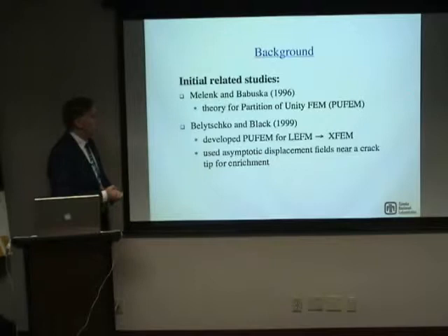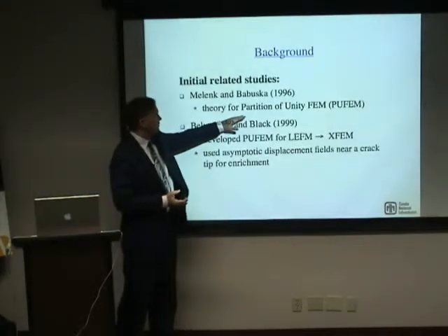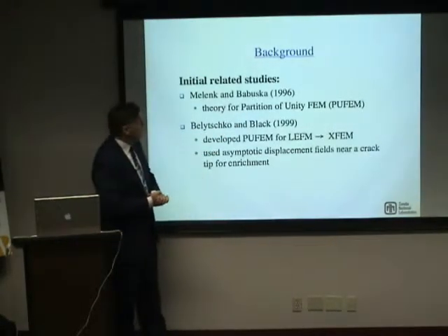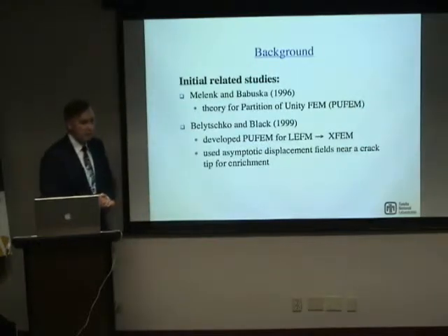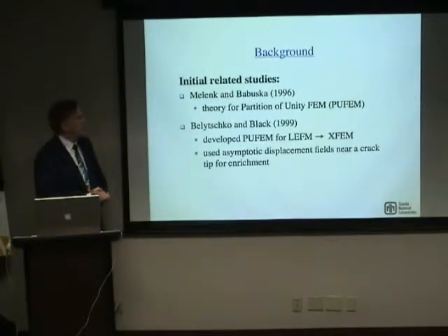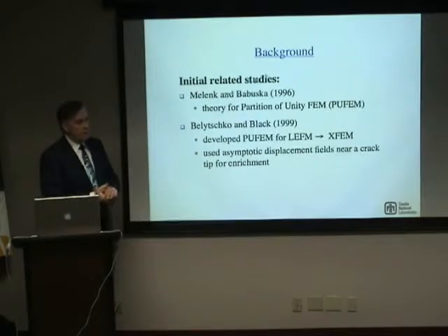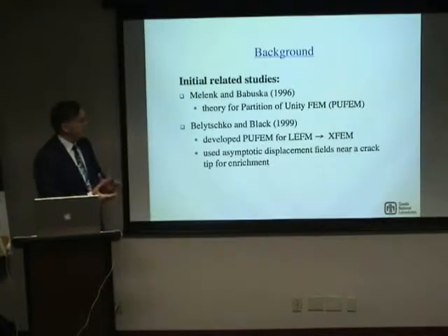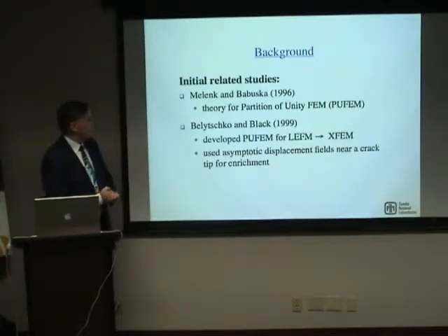And just in brief, and if you want the full mathematical description of partition of unity, you can look at the paper. But in brief, what we're talking about is that there are basis functions that, when added together, think at the element level, think of your shape functions, have a value of unity at any point within the element, which is necessary for convergence to begin with.